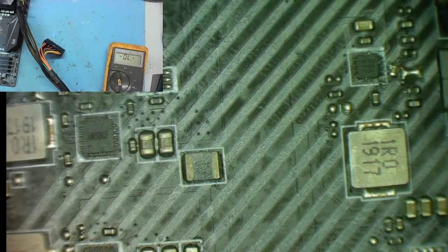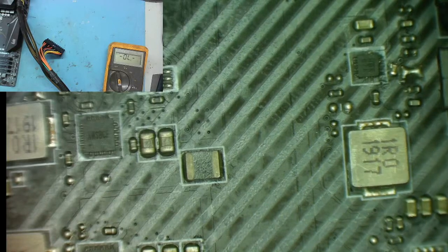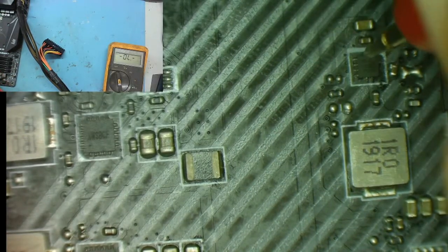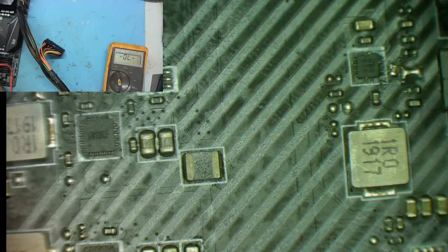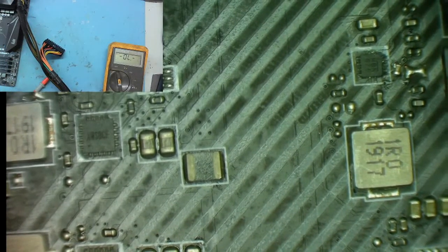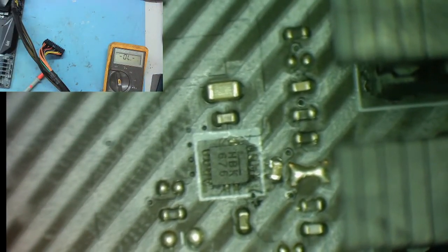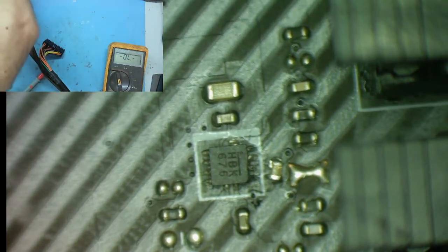But let's check. So meter on ground, yeah? And this is the 0.7 volts, it should be 1.8. No, it's a high resistance, there's no short there. So it's looking seriously now like this thing here has got a fault on it, giving too low a voltage. Can we find the data sheet for that one? That's the next thing we need to do. We zoom in. I think it says HBK 676. Okay, we need to find the data sheet for that. I expect that's an SMD code. I'm expecting that we'll have to somehow find the SMD code, then from that find the part number, then the data sheet.